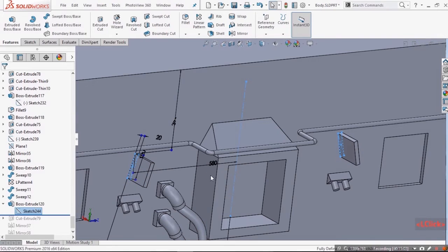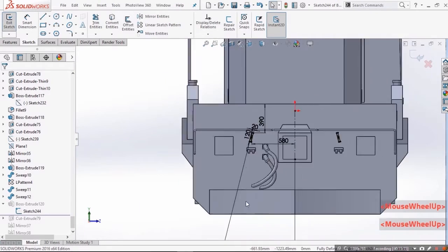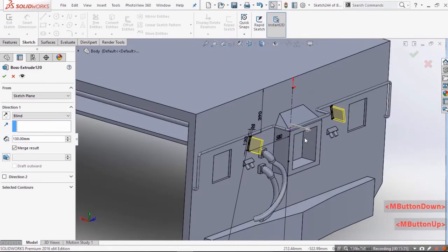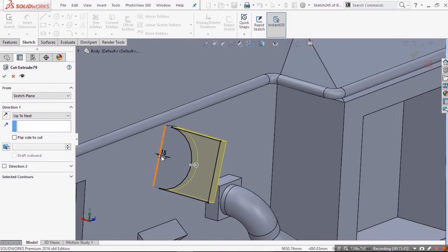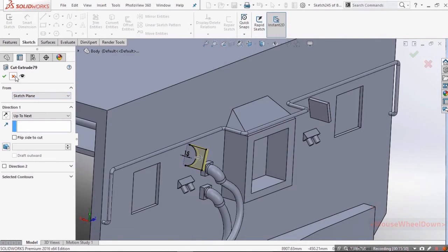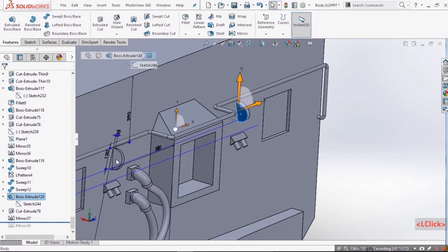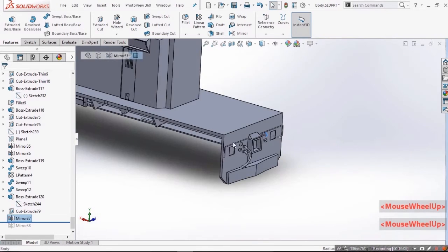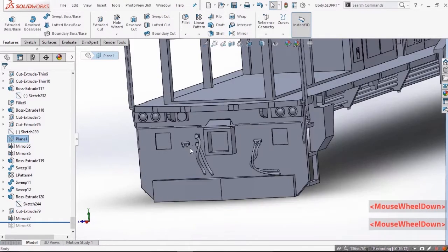Adding a few more final details here. You can notice that the sketch entities of this sketch are not exactly vertical or exactly horizontal. These are inclined at a particular angle with the vertical axis. And now I have removed the surface by giving a circular profile. And yes, obviously we need to mirror that cut on the other side of the center plane. And since we would require the recently made features on the front side, we would mirror it with the newly made plane.